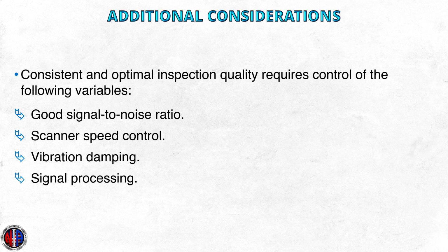Incorporating dampening mechanisms, such as shock-absorbing systems with big soft plastic rubber wheels, software signal processing, and so on, into the MFL system will help alleviate surface roughness vibration noise. Signal processing. Amplification of leakage field signals while simultaneously filtering noise created from the inspection scanning mechanism is required for maximizing discontinuity sensitivity.